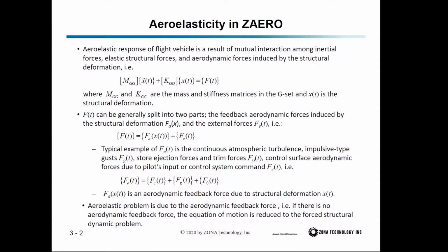The force F can be split into two parts. The first one we call aerodynamic feedback forces, which is induced by structural deformation, shown by F sub A, which is a function of x, and the external forces. Typical examples of external forces are gust forces, store ejection forces, trim forces, or the control surface aerodynamic forces due to pilot input command or command from the control system. So F sub A is an aerodynamic feedback force due to the structural deformation.